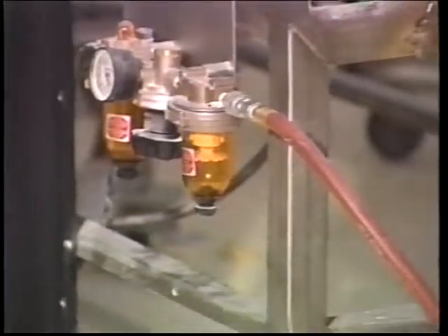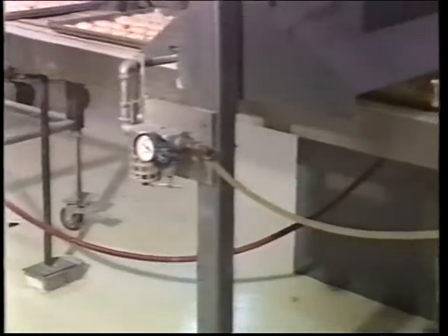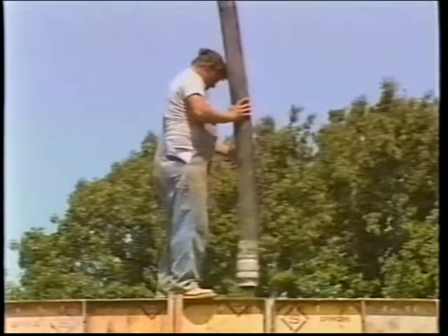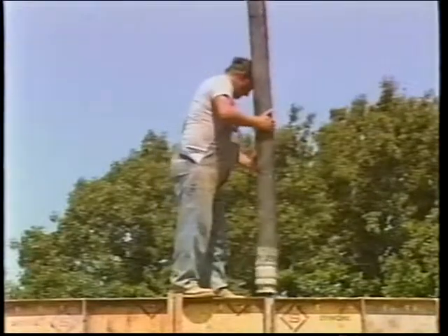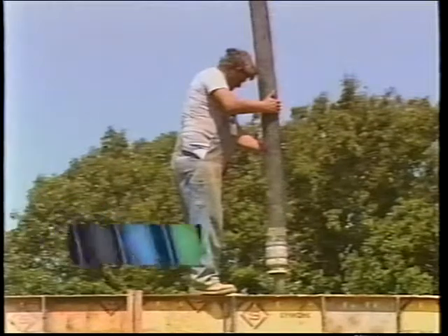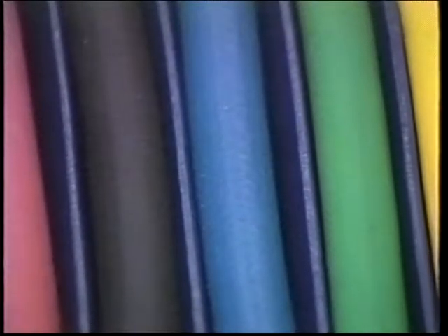Tube compounds are generally selected to have good resistance to the material being transferred, such as oil, steam, or chemicals. Cover compounds are selected to have good resistance to external conditions, such as abrasion, weather, and ozone. Therefore, it is very common for a hose to have a tube compound that is different than the cover compound. Tube and cover compounds can be a variety of colors, if desired, for a given application.